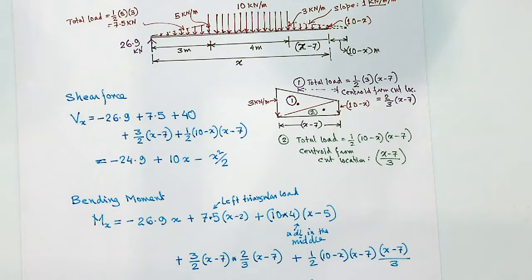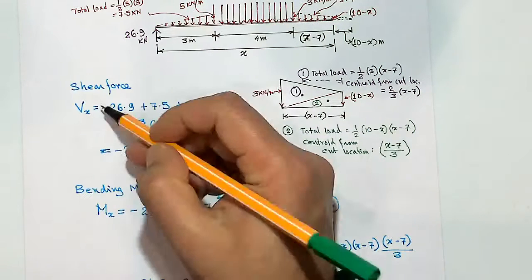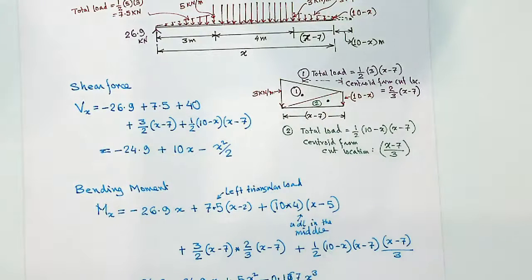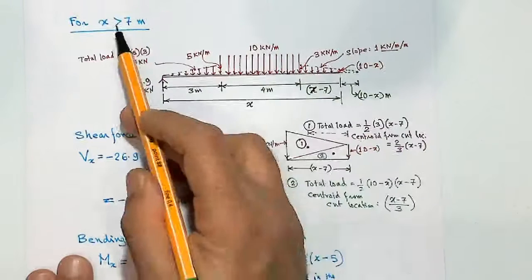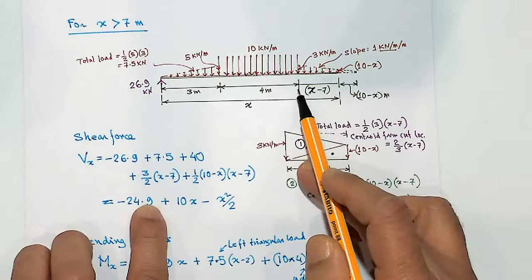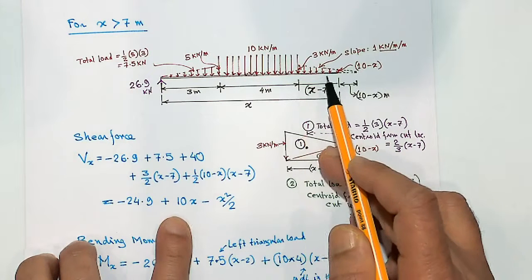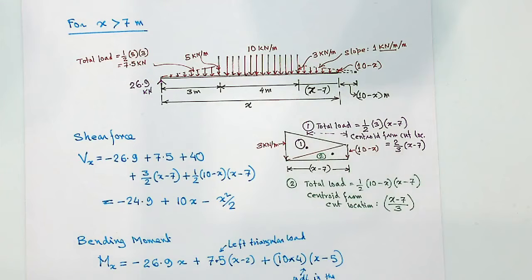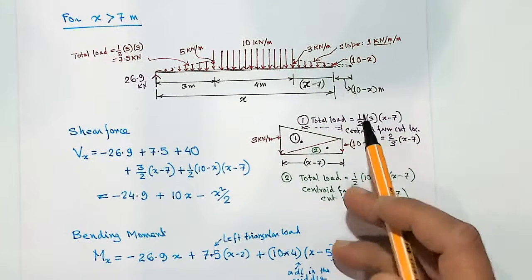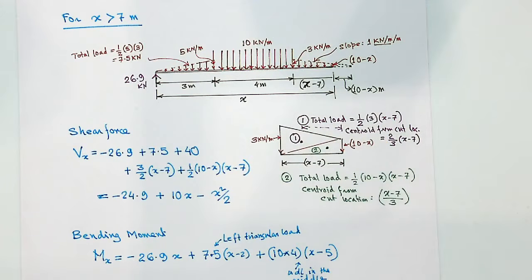So for the shear force and bending moment diagram, once you find the expression, then you vary the x value, and then you can draw the diagrams. So x in this case is from 7 to 10. You put in x equal to 7, you will find the shear force value at 7 meter. Then put x equal to 8. No, shear force not necessarily would be 0. Shear force at that end would be that reaction force, whatever, 25.9 or whatever we got.